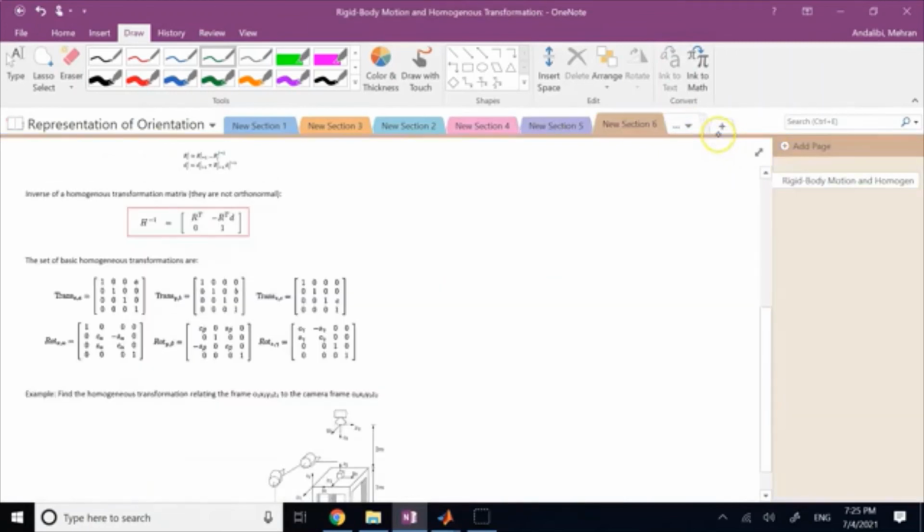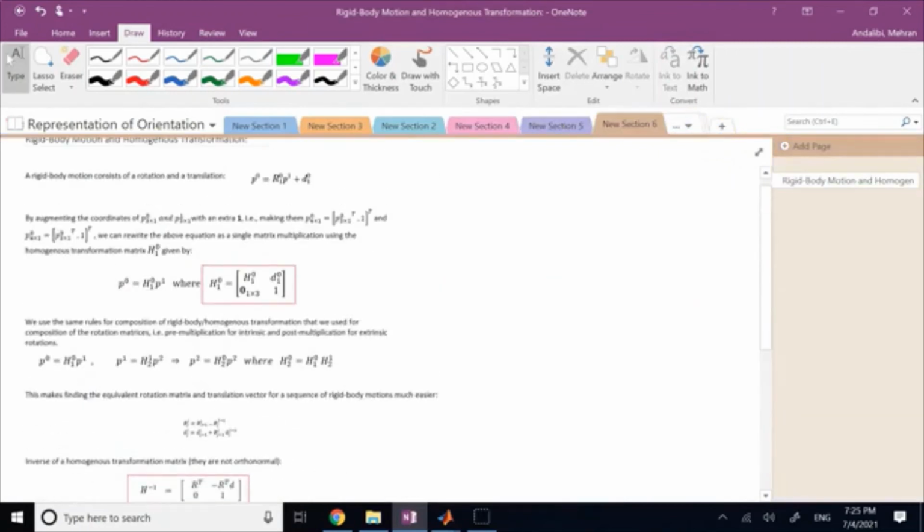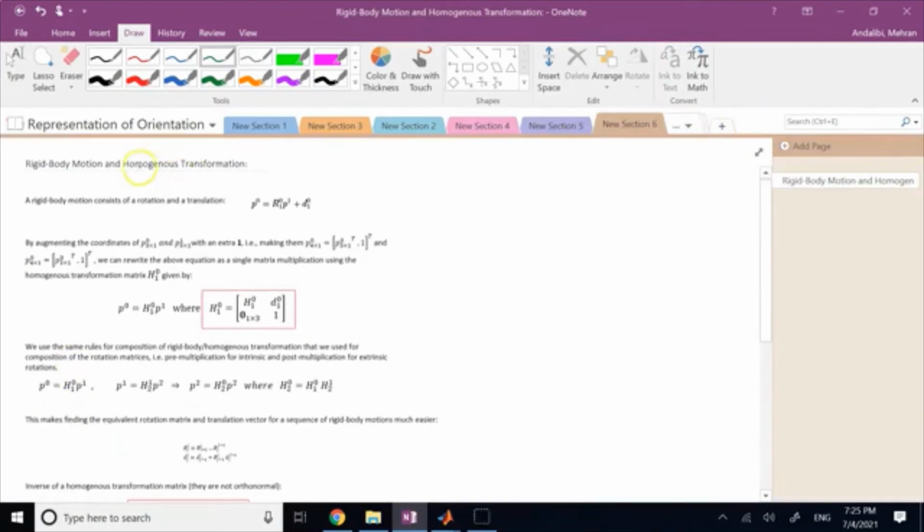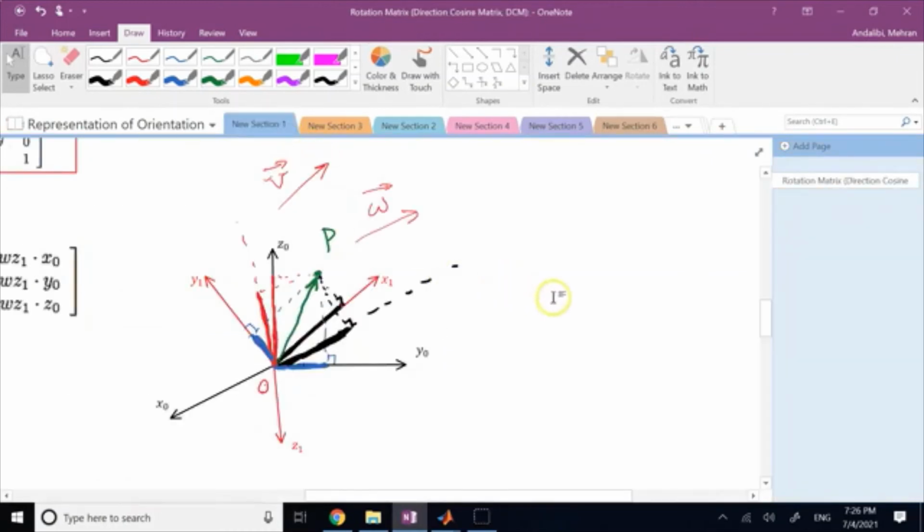And that's where you combine rotation and translation into one matrix, and we call it the homogeneous transformation matrix. I'll show you how to combine that displacement D with your rotation R, and actually, speaking of which, this is R, that's not H, and then go from one frame to the other when there is both translation and rotation.